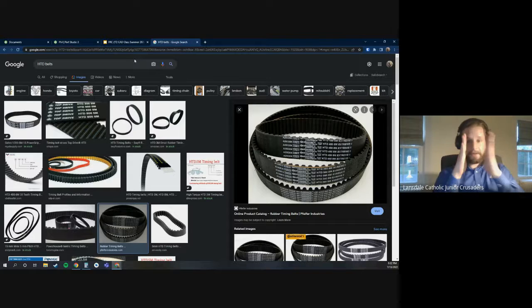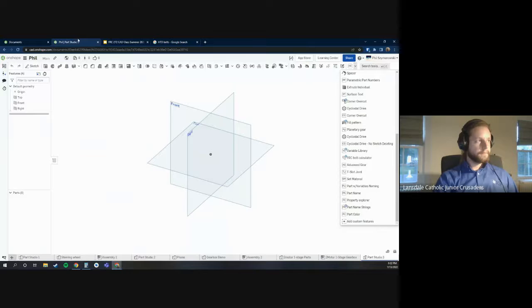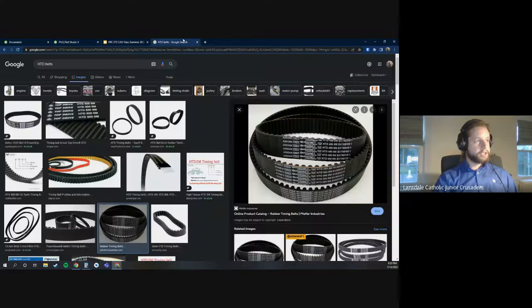Chains also have a thinner profile; the width of a belt is usually wider than a chain. So there's another kind of pros and cons. But generally speaking, belts are used commonly in the very first reduction from a motor to something in a gearbox to have a really high reduction in a small space while also saving weight.